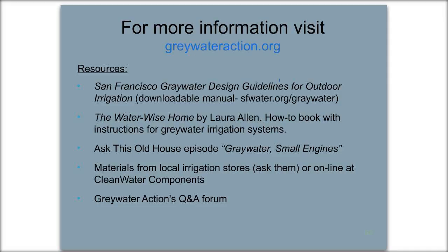What do you recommend for people who might be traveling for an extended period of time and not generating water? Yeah, so if you have a sophisticated, more advanced graywater system, it can just bring in other water supplies. If you have a simple graywater system, you have two options. You could ask someone to come water, or if you have a house guest, you could ask them to use your system. If you have an existing drip system, you could just keep it and shut it off for your graywater use, and if you go away for an extended time, you could turn it back on to have that backup.